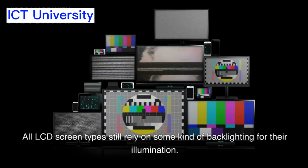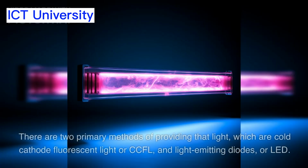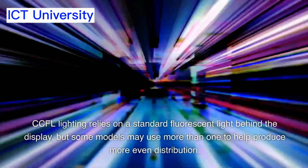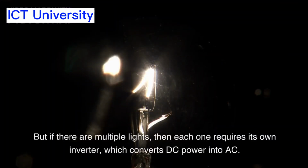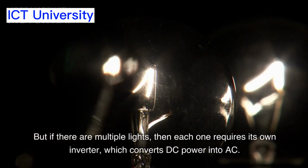All LCD screen types still rely on some kind of backlighting for their illumination. There are two primary methods of providing that light, which are cold cathode fluorescent light or CCFL, and light-emitting diodes or LED. CCFL lighting relies on a standard fluorescent light behind the display, but some models may use more than one to help produce more even distribution. But if there are multiple lights, then each one requires its own inverter, which converts DC power into AC.